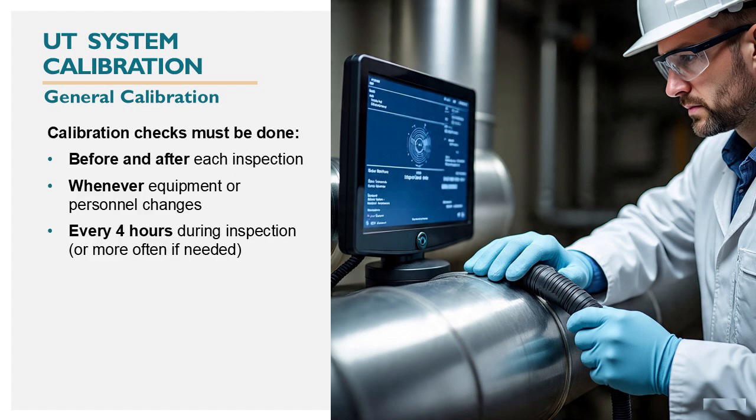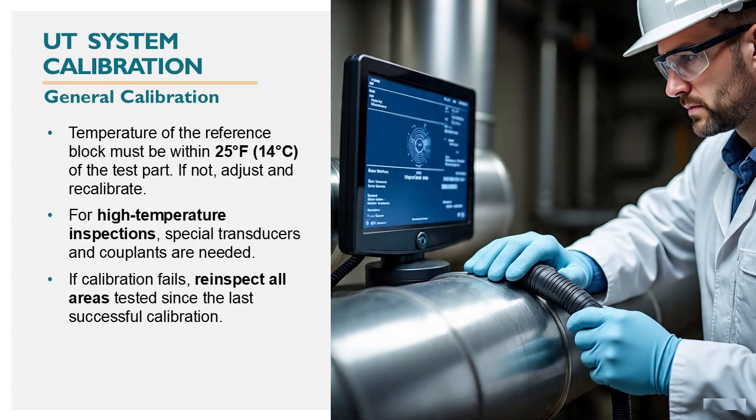In the UT system calibration, calibration checks must be done at the following times: before and after each inspection, whenever equipment or personnel changes, every 4 hours during inspection, or more often if needed. Temperature of the reference block must be within 25 degrees Fahrenheit or 14 degrees Celsius of the test part. If not, adjust and recalibrate. For high-temperature inspections, special transducers and couplants are needed. If calibration fails, re-inspect all areas tested since the last successful calibration.